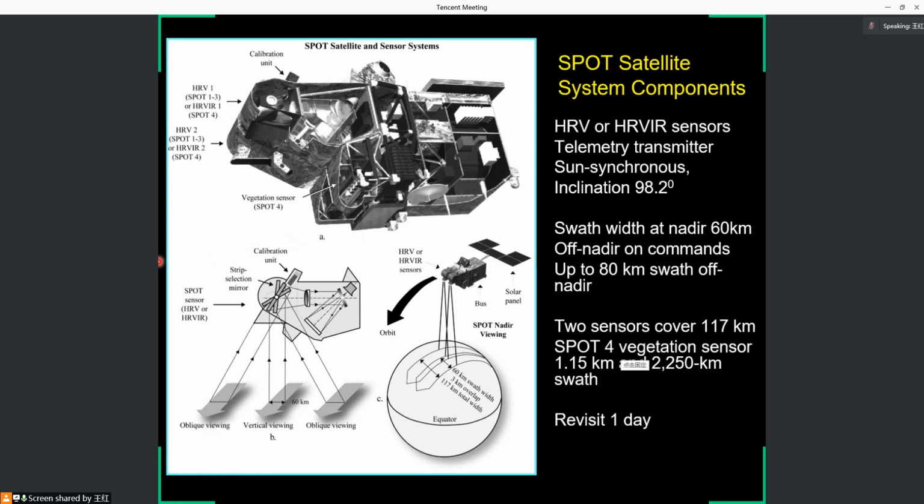Sentinel two is free and it's very good. The spatial resolution of the visible band is only 10 meters, higher than Landsat. It's very good. Also, it has a radar band, which can be used in rainy or very cloudy conditions. And 10 meter spatial resolution for the visible band and near infrared band.